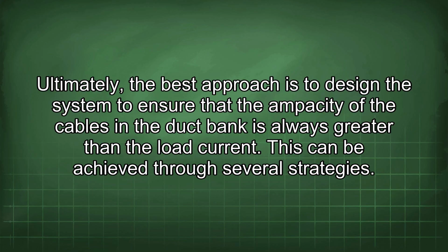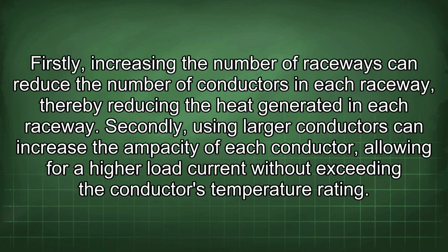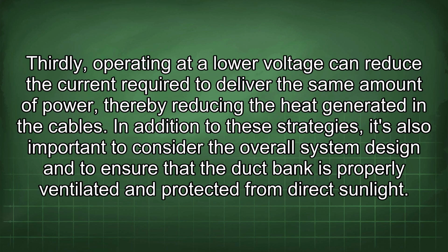This can be achieved through several strategies. Firstly, increasing the number of raceways can reduce the number of conductors in each raceway, thereby reducing the heat generated in each raceway. Secondly, using larger conductors can increase the ampacity of each conductor, allowing for a higher load current without exceeding the conductor's temperature rating. Thirdly, operating at a lower voltage can reduce the current required to deliver the same amount of power, thereby reducing the heat generated in the cables.